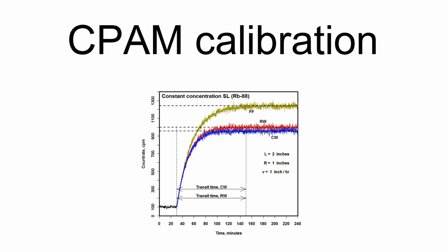An uncertainty analysis for the estimated quantity, concentration, release, uptake, is also part of the calibration process. Other performance characteristics can be part of this process, such as estimating response time, estimating the effect of temperature changes on the monitor response, and so on.